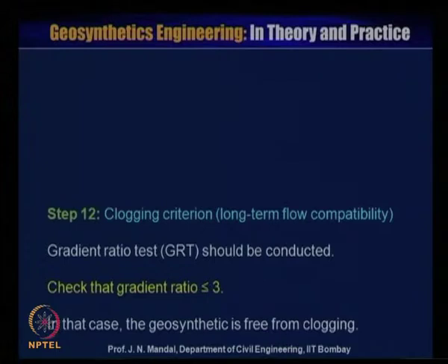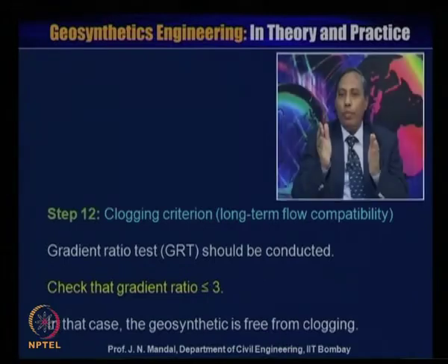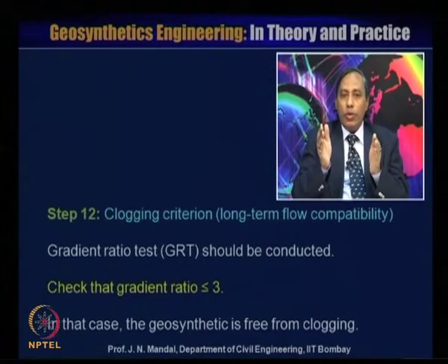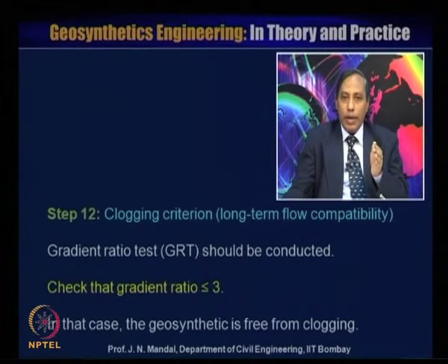Step 12, clogging criteria, that means long term flow compatibility. So, a gradient ratio test or GRT should be conducted and check that the gradient ratio value is less than or equal to 3. In that case, this geosynthetics is free from clogging.